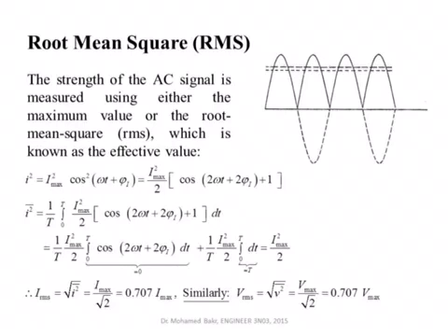One important property of AC signals is the concept of the root mean square, RMS. In electrical engineering, usually when a phasor is given without determining the nature of the amplitude, we call it RMS. What does RMS mean? If you have a sinusoidal signal, what we do is, as the name implies, root mean square.